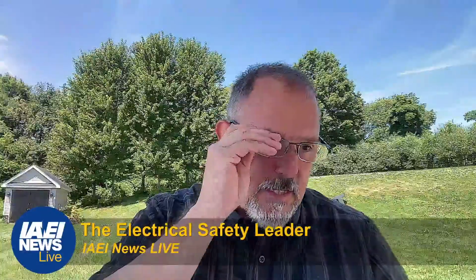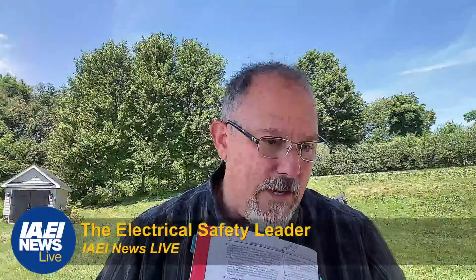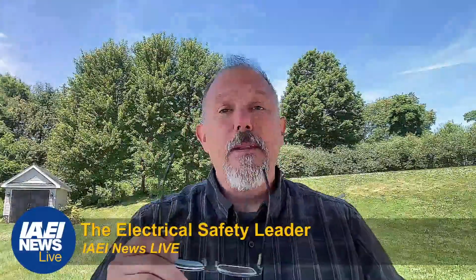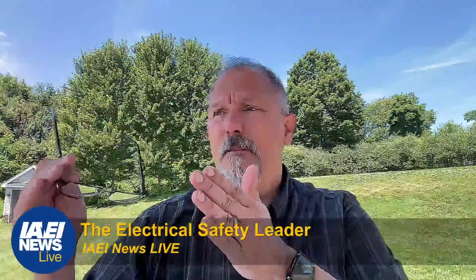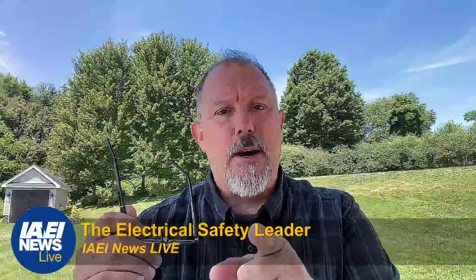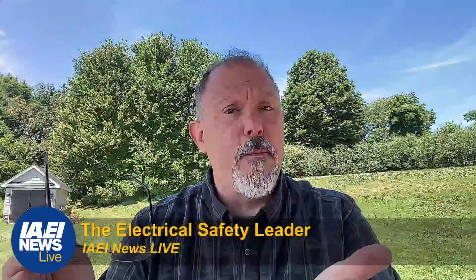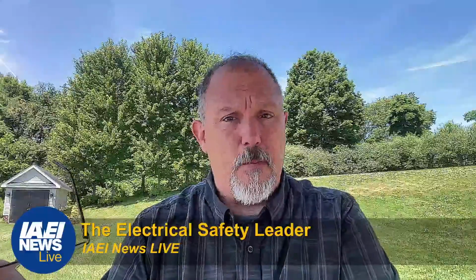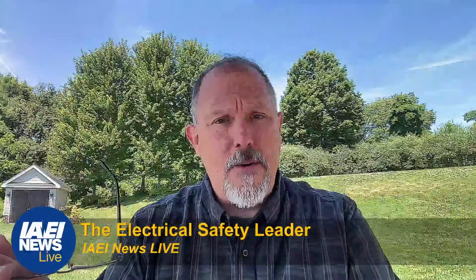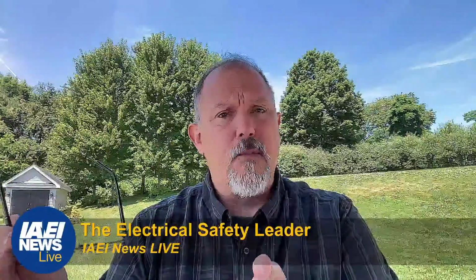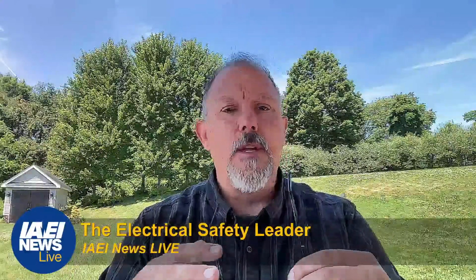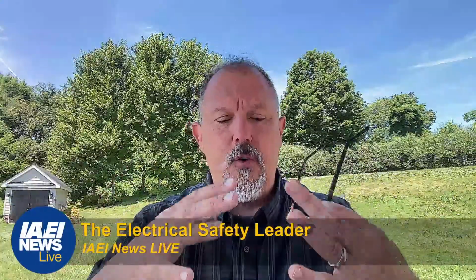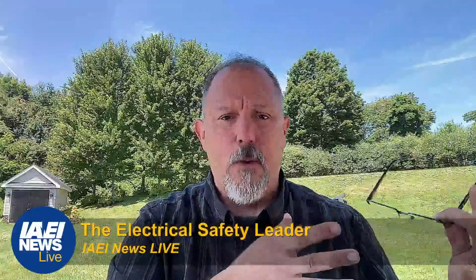Willie Snyder says, I always tell my apprentices, are you locking it out at the right sources and all sources? Absolutely. Now that's the electrical side. Then you have the mechanical side. And we're going to talk a little bit about the stored energy, say from a power circuit breaker or an insulated case circuit breaker. But there are many other areas of stored energy that you have to think about, rotating equipment and things like that. So it's really important to understand lockout tagout and the whole process of establishing an electrically safe work condition.